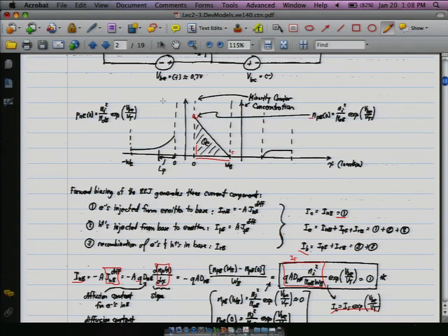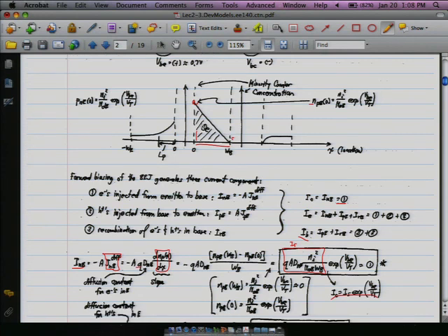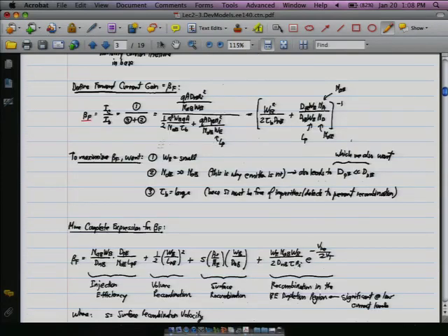And it turns out that we can actually start to modulate the base width by changing these depletion regions here, which we can do by applying a bias. So we'll get more into that in a bit. But that's why we actually focus on the fact that we want the base width to be small. And this also is done in fabrication. You keep the base as small as possible so that you get higher gain out of your device.